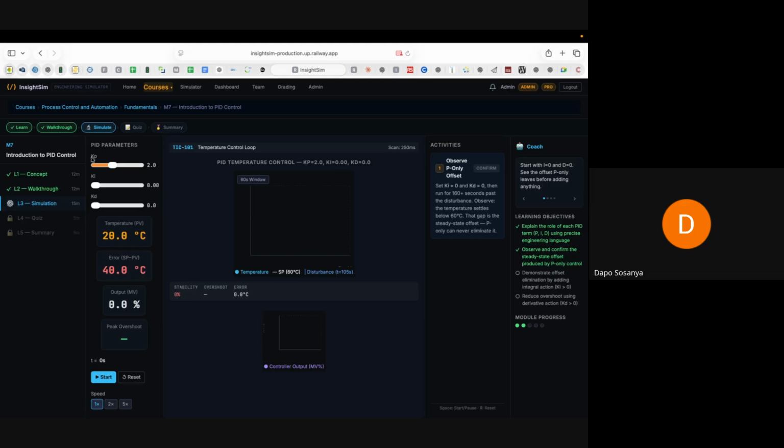Those actions determine what the valve will do in the event of failure. For some controllers, a direct acting controller, the minimum value it's going to give you will be 4 milliamp. The maximum value will be 20 milliamp.